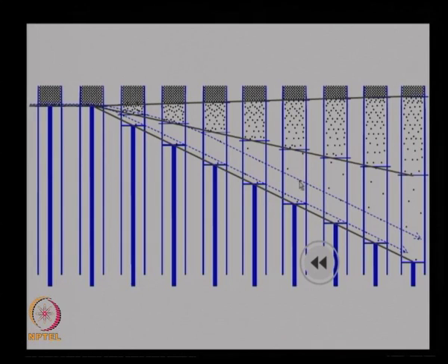And we are also tracking another particle, some other streamline, a slightly higher streamline, that starts almost close to that one, and it is coming here and getting accelerated. Since it is slightly higher, it experiences the expansion for a slightly longer time. It is stretching inside, the gap is increasing here, and finally it will come out from here, and then you can again see the particle here, here, here. It is just moving at a constant velocity parallel to the wall, if you imagine the 2D case.